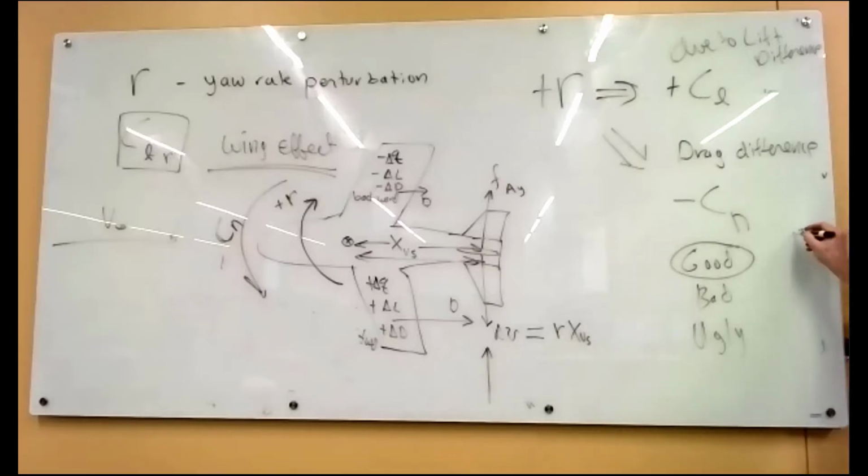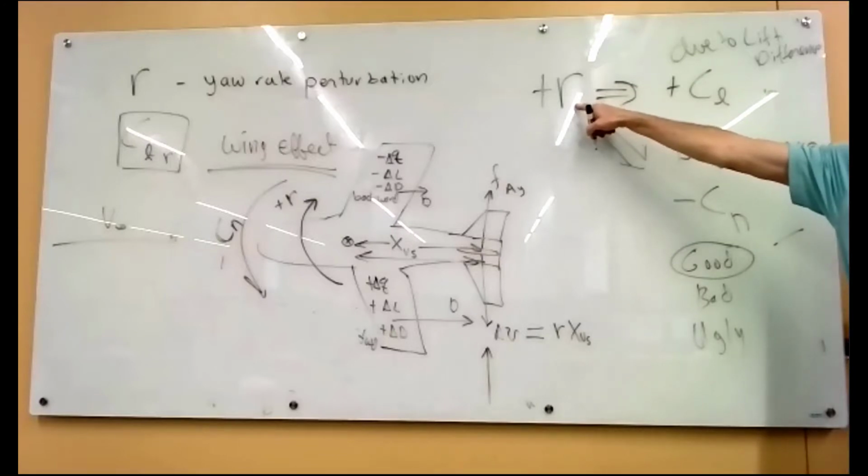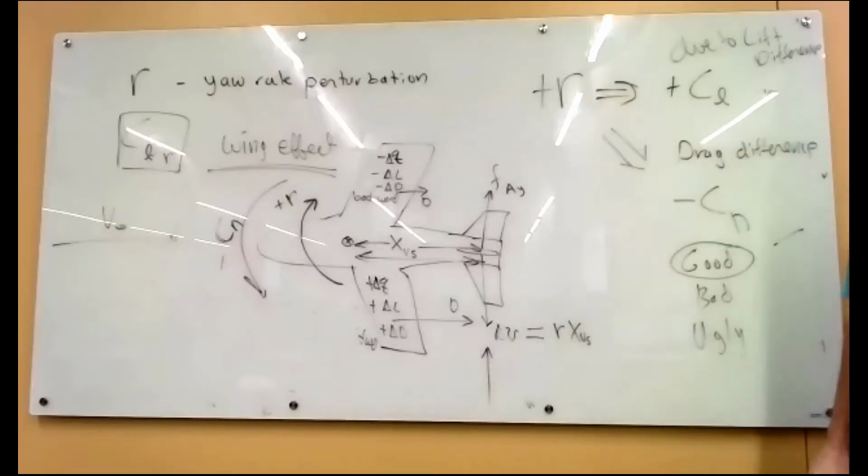Is there any stability effect of rolling related to a yaw rate? It doesn't really roll away from the yaw rate. It just rolls. So the answer is not really. It's a side effect, or that coupling that we were talking about last time. The same thing with a rolling rate: a roll rate produces a yaw.